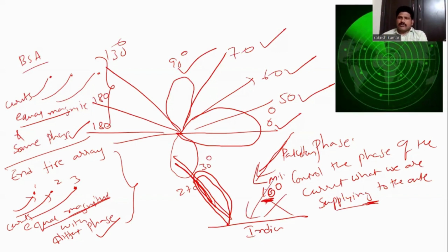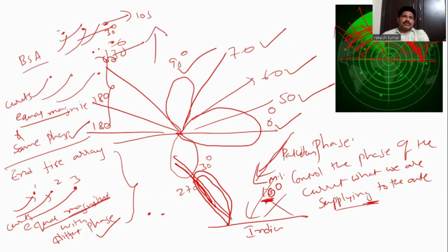That is why, if you observe in this diagram, there is continuous monitoring. This radar will check in this direction and keep fluctuating across directions, so the signal radiates in all the directions. For example, I take three connections, and for this set of antennas I make the progressive phase shift 30 degrees. Another three antennas I make for 60 degrees. I keep this antenna for 10 seconds, then for the other 10 seconds I keep the 60 degrees antenna. Then you can generate signals in 30 degrees, 60 degrees, or any direction.